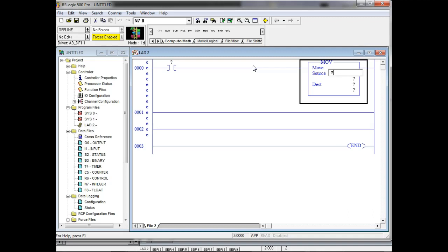So if I send information from thermal switches or something into the PLC, it would be considered binary. And that's not the same, guys. So what we'd have to do is convert them back over. And then if I wanted to send it out to a display, most of your displays are BCD. So you need an instruction where you can convert binary over to BCD. So it's those two instructions. So here's our move instruction.